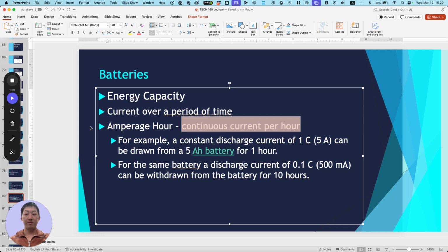From small to big, we have XT30, which is what we have on these batteries. You can read it if you look closely. Then we have XT60, our standard size that you'll probably find on typical batteries. For instance, this FPV drone uses an XT60.